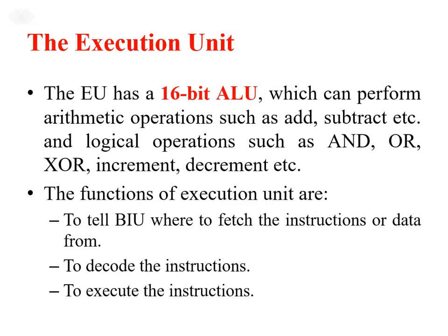This EU has a 16-bit ALU which can perform arithmetic and logical operations. Arithmetic operations such as addition, subtraction, division, multiplication, and logical operations such as AND, OR, XOR, increment, and decrement. So the functions of the execution unit are to tell the BIU where to fetch the instructions or data from, next to decode the instruction, and last to execute the instructions.